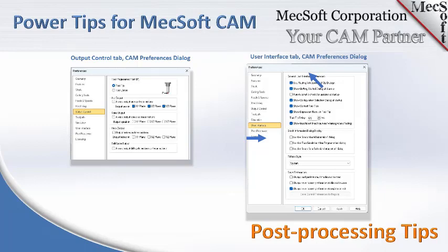Your machine has a built-in canned cycle that understands what the codes are. If your machine doesn't, you can convert your drilling to linear motions, where it's just straight point-to-point, simulating the same drilling operation, but just using G-code coordinate motions to do that.